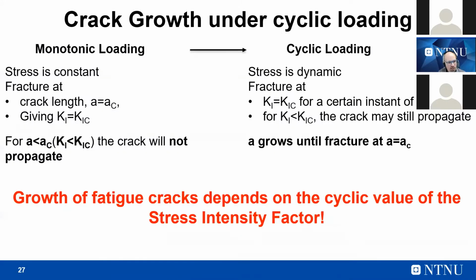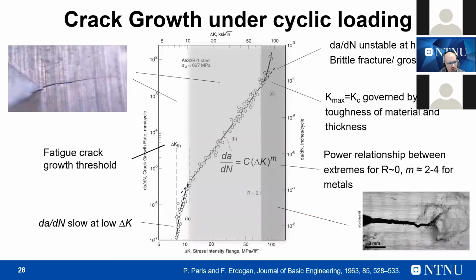Why am I mentioning this? Because the most important curve that we know that is able to describe the propagation of a crack is due to Paris and is called the Paris curve, and it is the curve reported here in this slide. In this curve we have three different regions. The first region is on the left side, the initiation phase, where a crack is initiating, and we have a threshold value below which, even if we have a crack, nothing is propagating. After that the crack starts to propagate in the middle part of the diagram, where we can use the so-called Paris law, reported in the center of the diagram. And after that we have the static failure on the right side of our diagram.